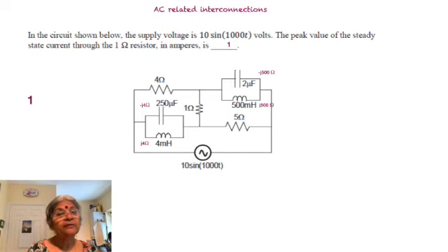Together it's very clear that that's going to be minus j4. So when j4 and minus j4 are in parallel, the numerator is fine, but the denominator talks about j4 minus j4. The easiest thing to remember is R1 R2 divided by R1 plus R2. So we have j4 minus j4, which is 0, which means infinite impedance.